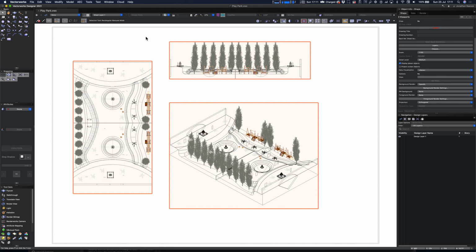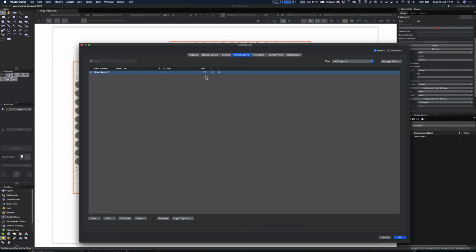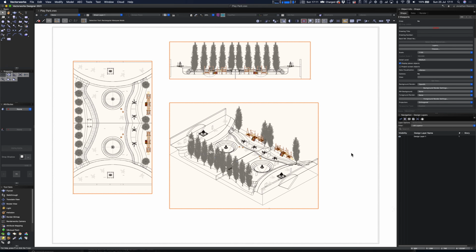Click Update. Just before we do though, do remember, if you're going to do some renderings, you want to make sure that you up the quality of your sheets. I don't need to go that high to begin with. Let's go 300 dpi, that's pretty high. But depending on the print quality you want, you can take it as high as you would like, within reason. But do remember, adding dpi adds render time quite significantly. You quadruple the render time every time you double the dpi.